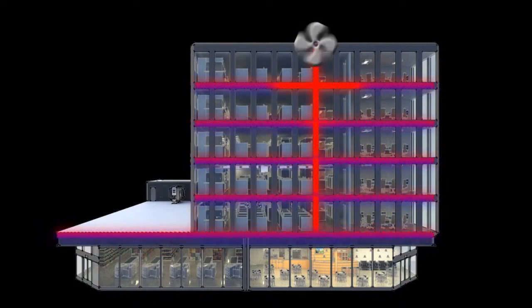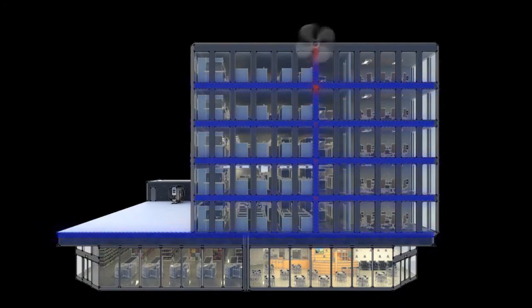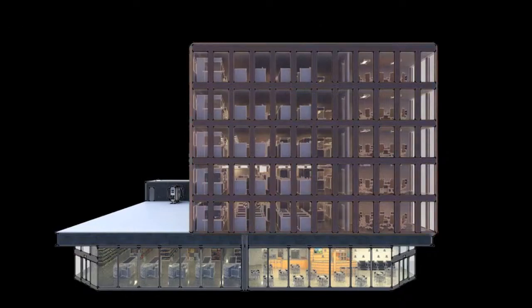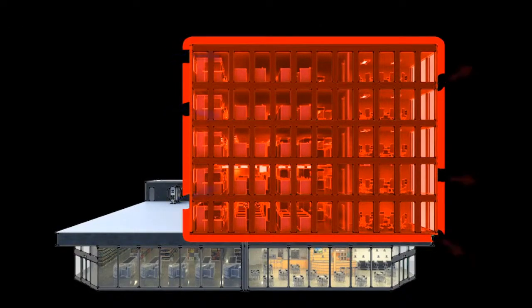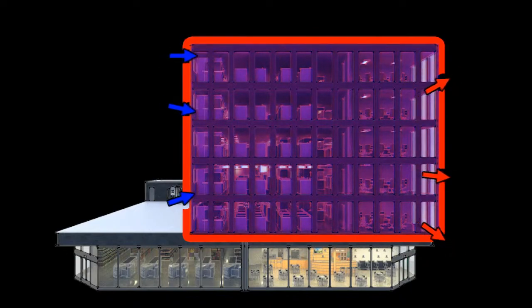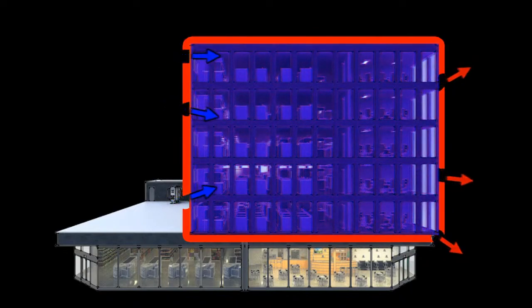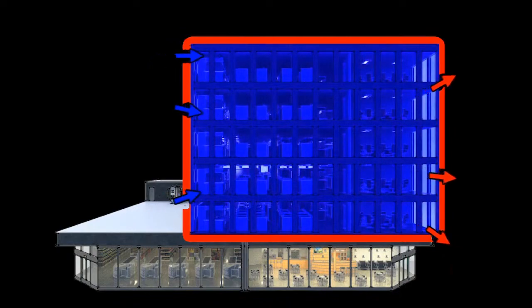So the common factor across all these mechanisms is the presence of holes in the building envelope, through which uncontrolled air movement can occur. This air movement can not only significantly reduce the energy performance of the building, but introduces a discrepancy between the as-designed and as-built performance that can lead to complex and expensive remedial action. It's therefore important to ensure that the air barrier system used is robust and flexible enough to perform as designed, both initially and throughout the building's life.